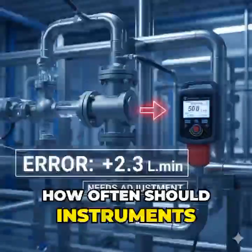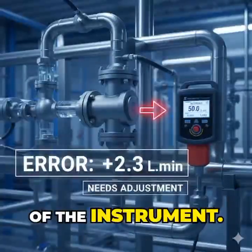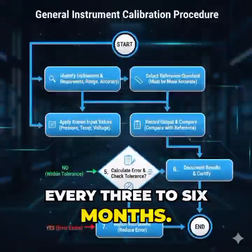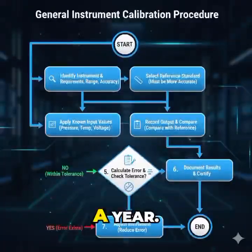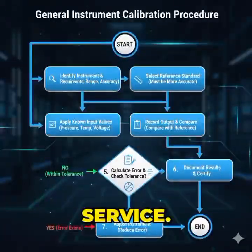5. Calibration frequency. How often should instruments be calibrated? This depends on industry standards and the criticality of the instrument. Safety-critical instruments are usually calibrated every 3 to 6 months. Normal process instruments are often calibrated once a year. New or repaired instruments should always be calibrated before being put into service.